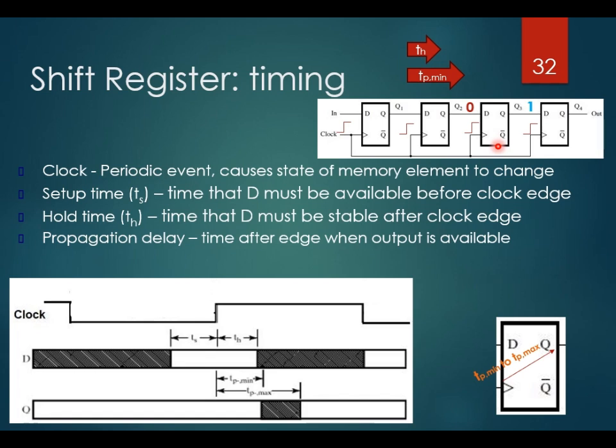And then if the clock period is long enough, this 0 will reach Q2 earlier, before the setup window starts counting towards the next clock edge. In other words, because the clock period is long enough, by the time the bit 0 moves from Q1 to Q2, it still reaches earlier, before the setup window starts for the next clock edge.